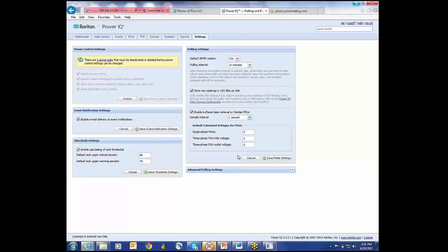And what it does is internal sampling at a 1-second interval. Each one of those 1-minute samples has an internal sampling rate from the PDU at 1 second. And therefore it creates a max, min, and average for that 1-minute interval based upon a 1-second sampling, making it more likely that you're going to catch maximums and minimums. In addition to that, the Raritan intelligent PDUs have an energy chip that is billable grade energy level such that it provides information with less than plus or minus 1% error. So that's not even sampled, that's just collecting those readings like a meter reading.